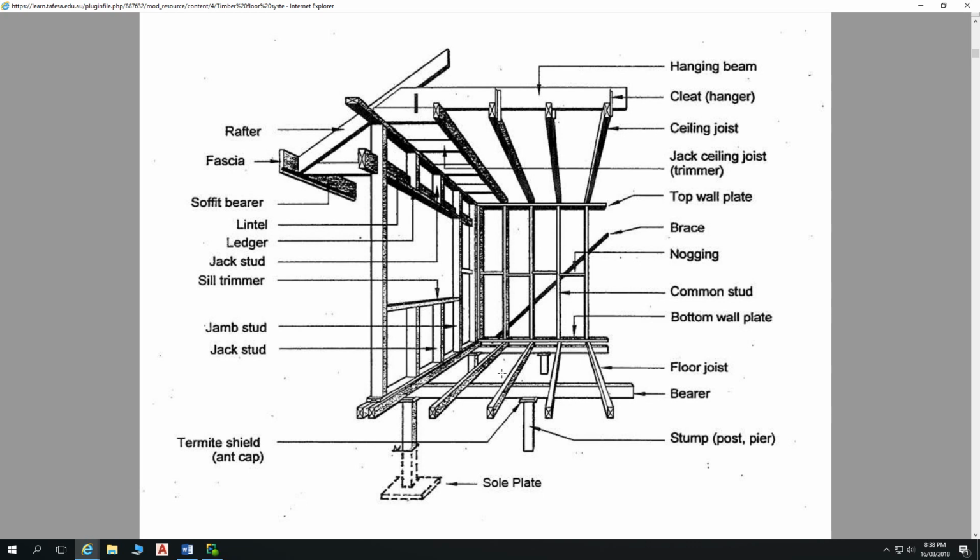Platform flooring is much quicker because you put down your platform flooring when it's all just joists and it goes in straight away, and you've got this lovely level platform for doing all your wall frames and for tilting them up. Works very well on site. Look, I certainly advocate for platform flooring as opposed to fitted flooring.